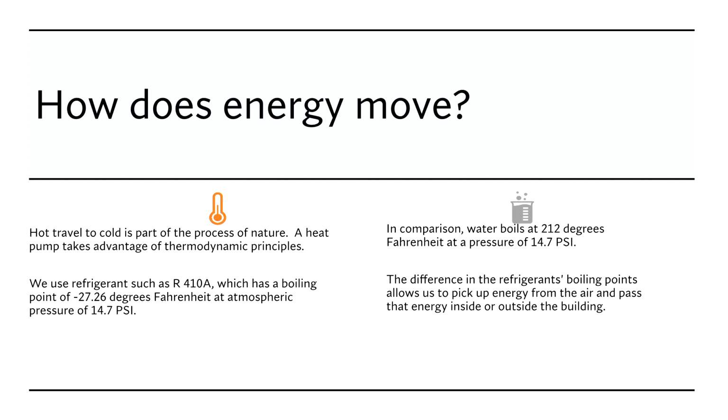That is 47 degrees of heat that we can add to the refrigerant to cause it to evaporate or change from a liquid state to a vapor state. And when we do that, we're picking up energy. Then we're just going to move it. Okay, we're going to use a compressor to move it from place to place, and then we're going to have a condenser that's going to reject the heat out of the system. Talk about a little more of that coming up.